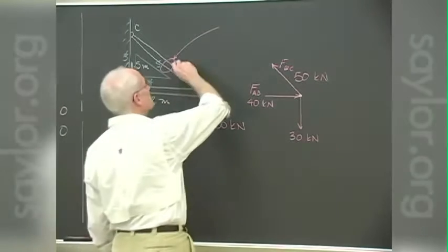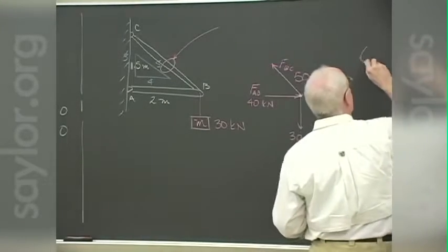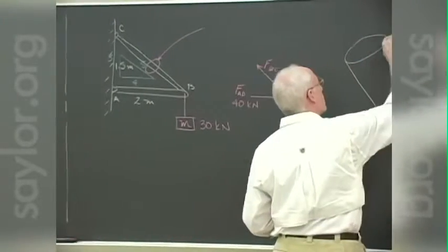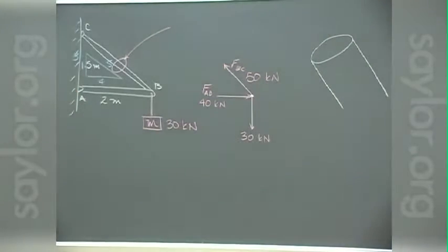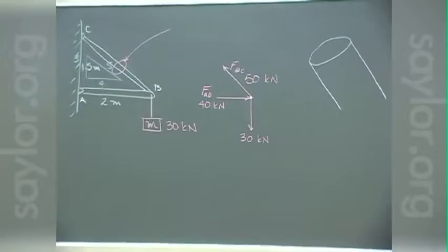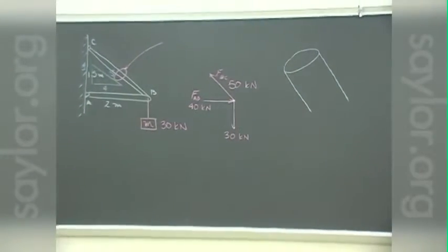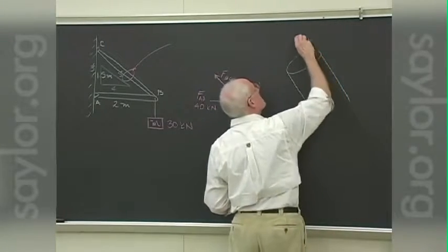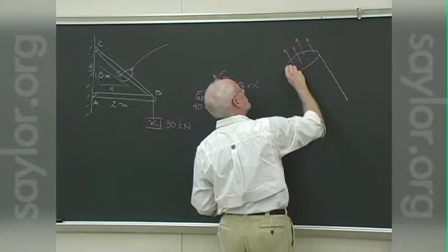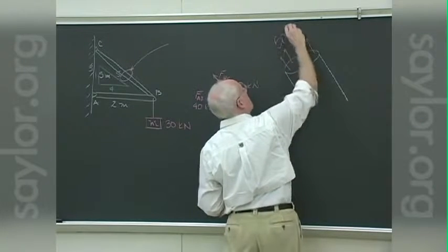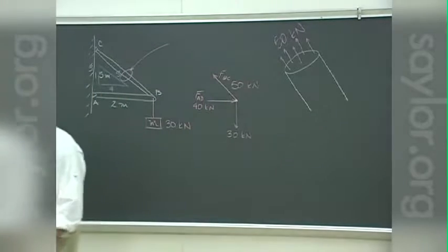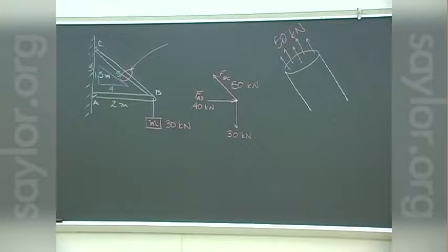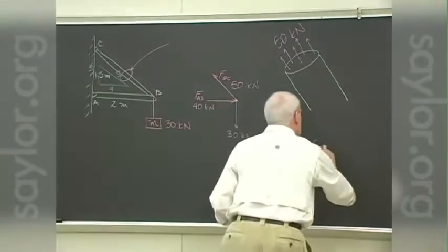So if we bring this little piece over here, kind of blow it up there so that we can see it, in that case, the 50 kilonewton load is acting throughout this entire piece, and in fact it's spread over that entire cross-sectional area. We'll only draw it for the most part as a single point load.